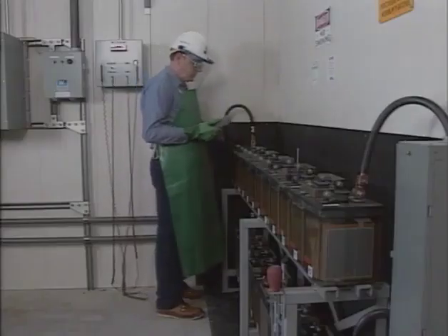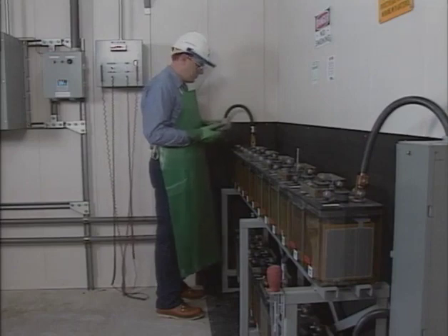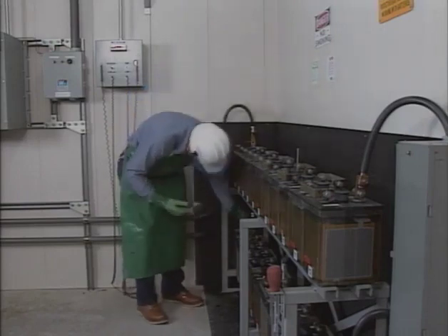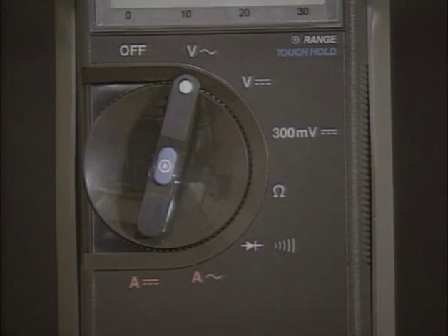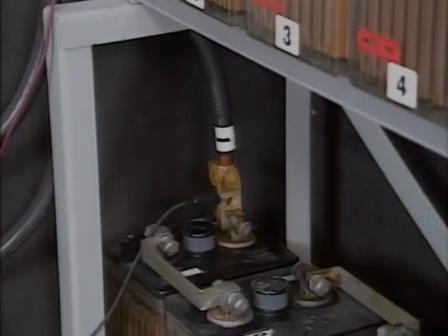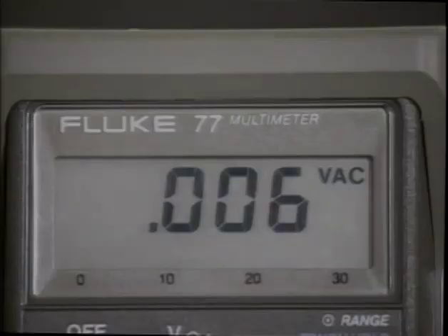On a periodic basis, it's a good practice to check for AC voltage at the battery. If a charger starts to go bad and loses its ability to convert AC to DC, it will show up at the battery. A meter, such as this digital volt-ohm-meter, can be used by setting it to measure AC voltage and placing the test probes across the terminals of the battery. The AC voltage reading here is within reason. If a charger is going bad, there will be a large AC voltage output from the charger, and the charger would need to be replaced.